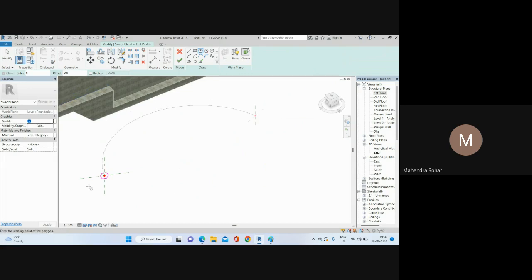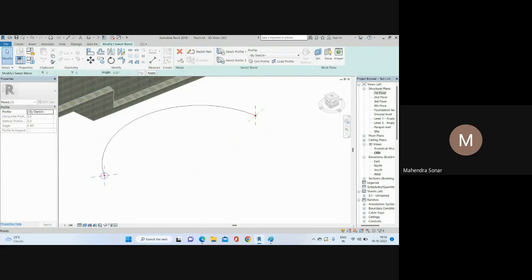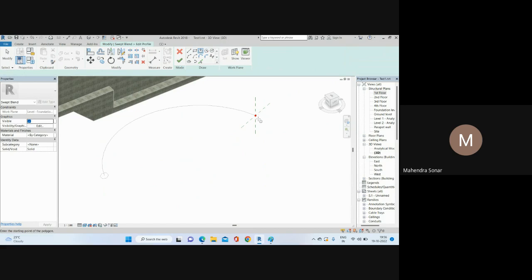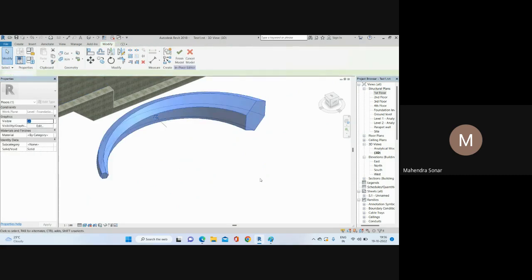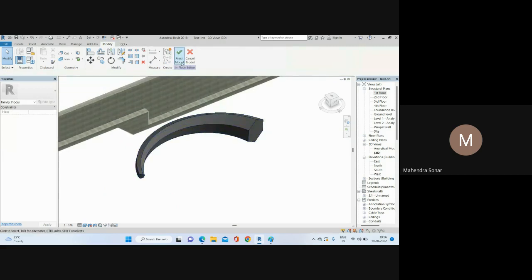Okay, so once you complete here, then same for profile 2. Edit Profile, then go to the hexagon here and just add your profile like that. Just consider this is 8 meter. Once you are done with your profile, click OK and OK, so you can see, and Finish.